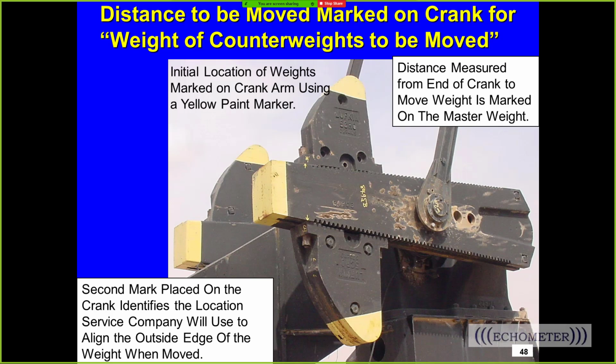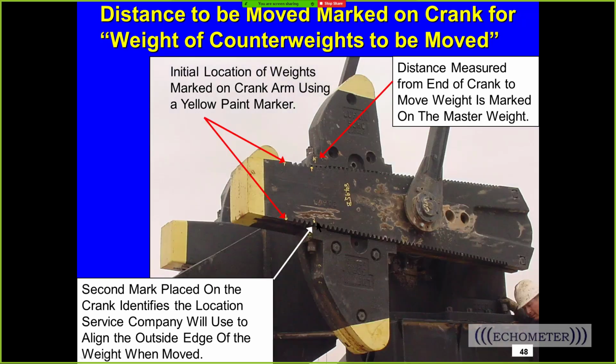Now this is a well out in West Texas, and you can see that we did some net torque calculations, and we marked on the crank where the weights are, and then we marked where they should be moved to balance the gearbox loading. I really like this idea.